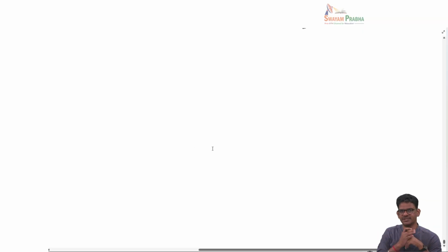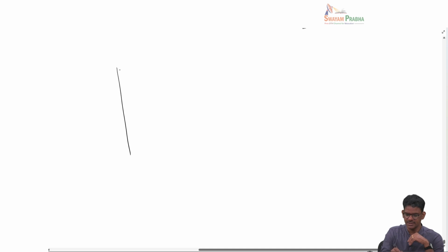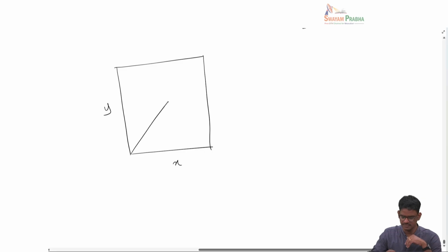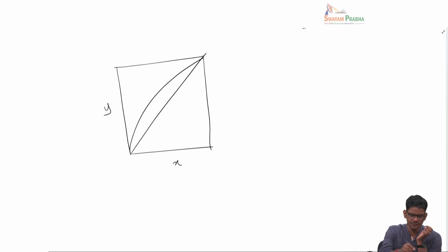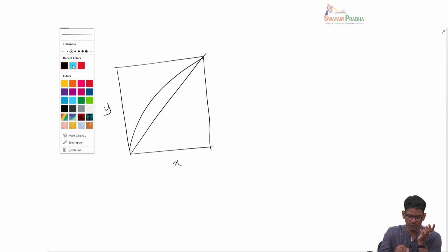I'll talk about this calculation in the next class, but just to sensitize you, what we are hoping to do is have the equilibrium diagram. As I said, for any design calculation, the equilibrium line is very important. Here the equilibrium line is Y versus X. It relates the vapor to liquid composition at equilibrium. And we will draw two operating lines, because the distillation column involves different flow rates.